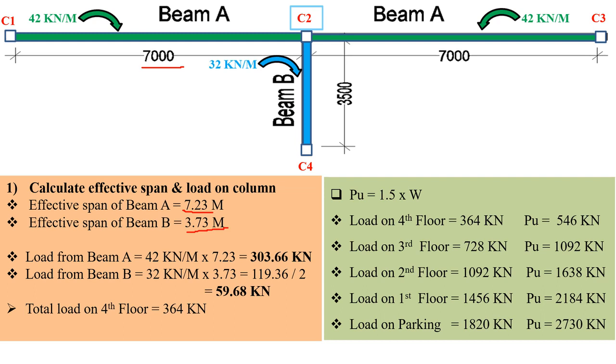When I need to calculate the load of the complete beam A, one very important thing to remember: you are calculating for the column C2. This column is going to be abutted by three beams. So let me talk about beam A. Beam A is supported by two columns, C1 and C2. The complete load of the beam is not going to come on the column which I am going to design. It is going to be half on C1 and half on C2. That is one of the most important points which we need to remember.